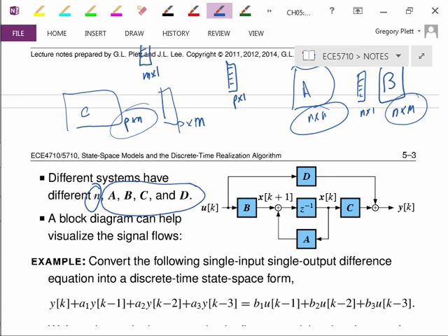It can be helpful to use a block diagram to visualize how the model is operating. This block diagram is something that you could implement directly in Simulink if you desired to do that, and if you understand Simulink. The z inverse block simply means unit delay. So the input to the block is delayed by one time sample to get to the output. And if x[k+1] is a future state, then x[k] is the present state, then the delay of the future becomes the present.